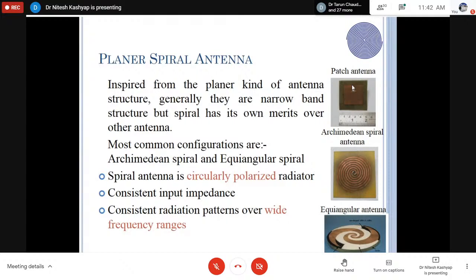the metallic portion and the slotted portion input impedance, if we multiply both of them, it will be equal to eta squared by 4, and eta is 377 ohm, the free space characteristic impedance. So if we do the calculation with respect to a self-complementary antenna, it comes to 188 ohm. Okay, so